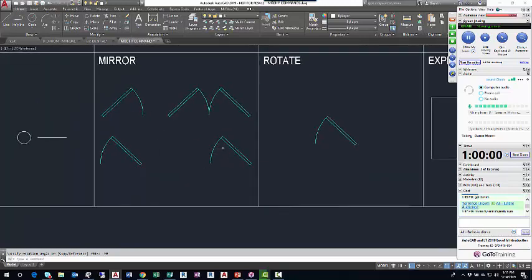Well, the door is asymmetrical, but not all doors will want to open from the left and be hinged on the right, or vice versa, open from the right and be hinged on the left. So you can use your mirror command. The mirror command is our next modify command, and I'll mirror the first door so I make a double door, right? I have ortho on. A lot of times when I mirror, I like to have ortho on so I get a nice straight, vertical transition.